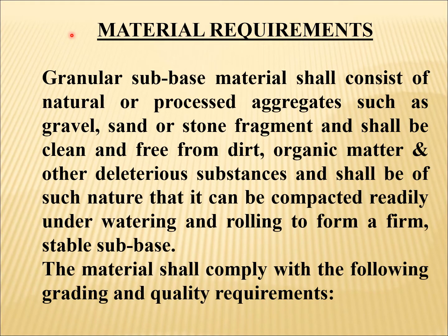Material requirements. Granular subbase material shall consist of natural or processed aggregates such as gravel, sand, or stone fragment, and shall be clean and free from dirt, organic matter, and other deleterious substances, and shall be of such nature that it can be compacted readily under watering and rolling to form a firm, stable subbase. The material shall comply with the following grading and quality requirements.